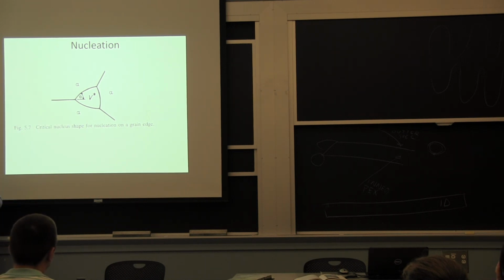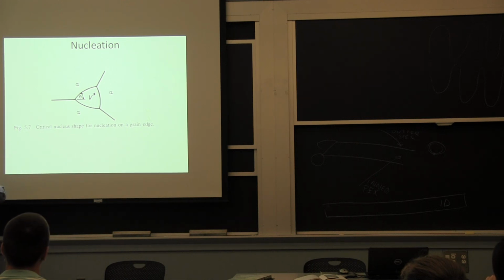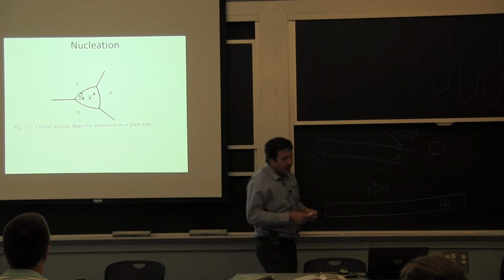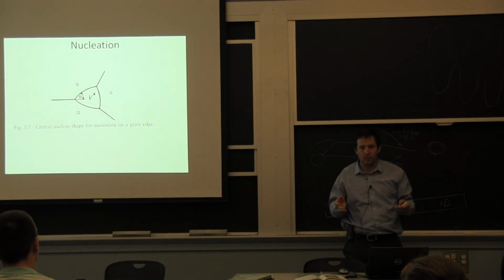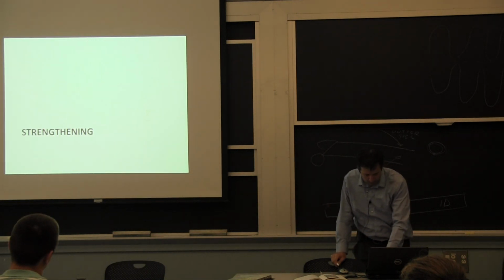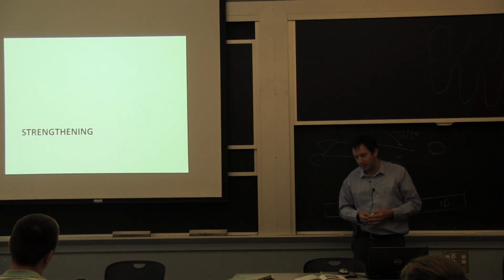And that happens again in polymer, where you just come and say, hey, I'm going to put this little inclusion, so I'm going to start a grain, a spherulite we call it, at this specific location, and it just keeps growing in all directions from there. So you try to utilize any interface that's existing in your material when you want to form precipitates or draw new grains. So we're going to talk about straightening.